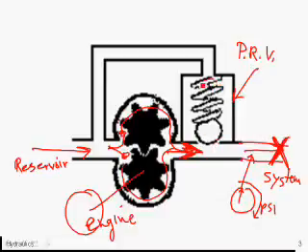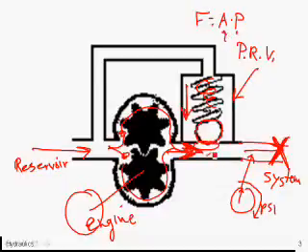And it works by having a spring pushing down on this ball right here, and this ball is closing up this hole. Now, you've got to remember, force equals area times pressure. The spring has a certain force pushing down. This hole down here has a certain area, and the pressure needed by this fluid in here to go against the pressure of the spring is set by the area of this hole versus the force of the spring. So at some predetermined pressure,